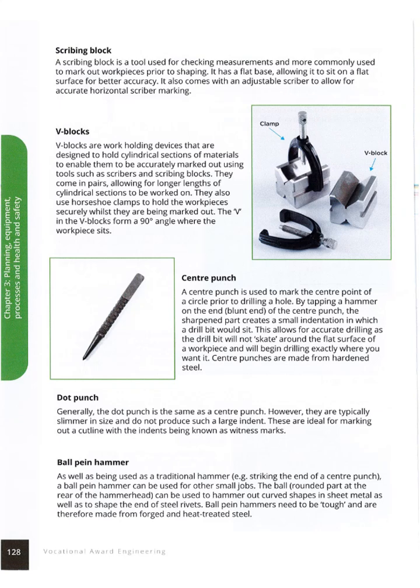Ball peen hammer, so this is a hammer that has a kind of ball at the back of it that can be used to shape metal. Again, you'd use the ball peen hammer to hit the center punch to make sure that you get those divots. Now flat files, something that